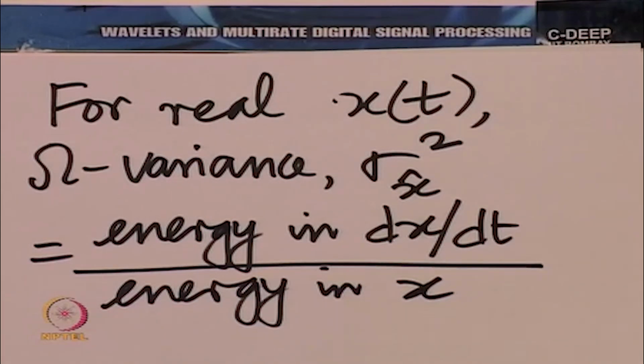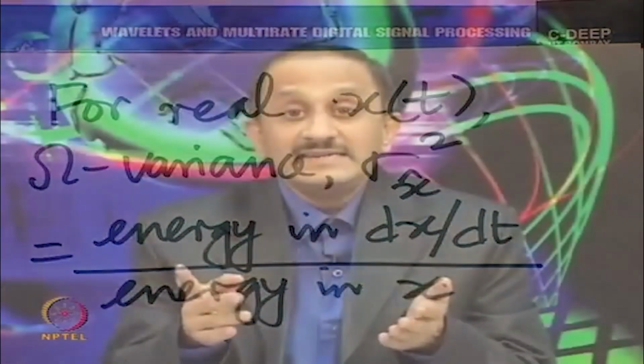And now, we have the answer why we ran into a problem for phi t. As you can see, phi t is discontinuous. So, when its derivative is considered, there are impulses in the derivative. An impulse is not square integrable, and therefore, the numerator of this quantity diverges.